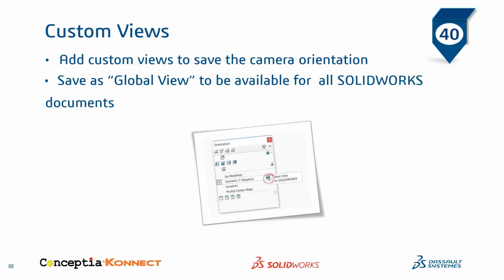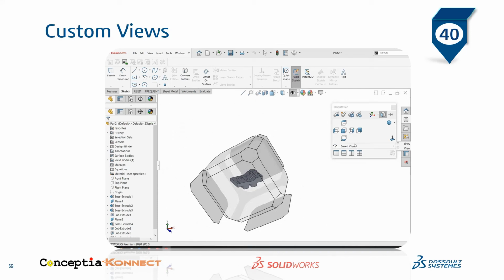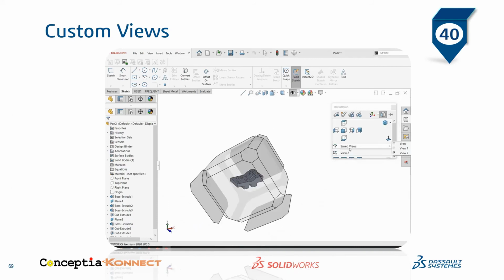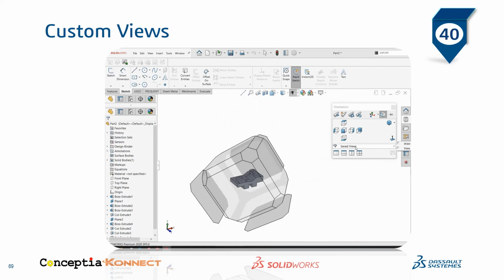Number 40. Custom views. Add your custom views to save the camera orientation and save as global view to be available for all SOLIDWORKS document. So you fix a view and create a new view. Give a name to it, select OK. Now save the view. So view 2. So in your saved views, you will have it. So this is custom views.